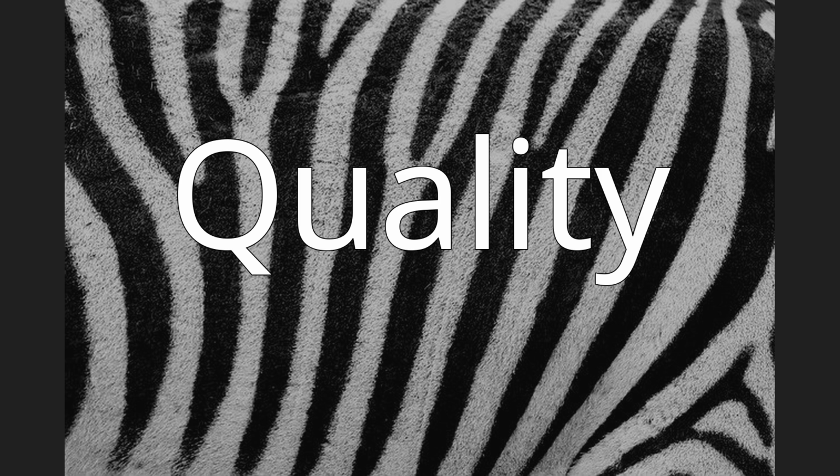Quality. The quality portion of the OEE metric represents the good units produced as a percentage of the total units started. The quality metric is a pure measurement of process yield that is designed to exclude the effects of availability and performance. The losses due to defects and rework are called quality losses and quality stops. Reworked units which have been corrected are only measured as unscheduled downtime, while units being scrapped can affect both operation time and unit count. Calculation: quality equals (units produced - defective units) / units produced.